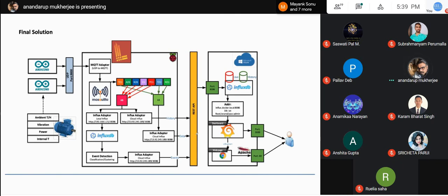So the moral of the story is, what were the lessons learned during this process, right? Some of the lessons learned: there is a fight between cost and accuracy. The lesser the cost, the more the accuracy is bound to suffer. Lower cost devices like processors are not going to significantly affect your solution, but the sensing is going to be significantly affected. The range of measurements is going to be limited.